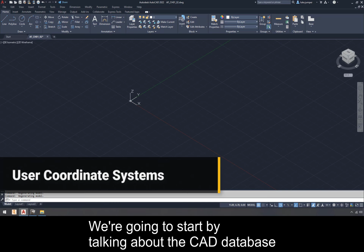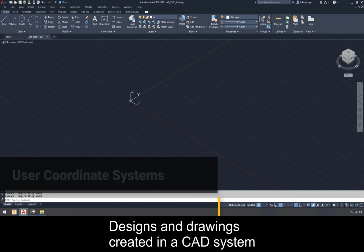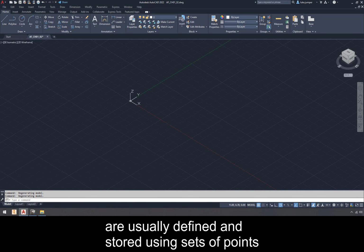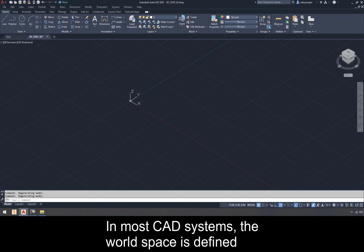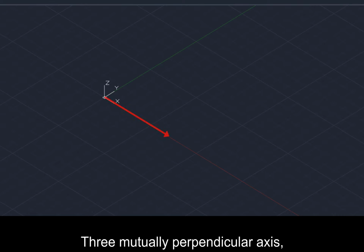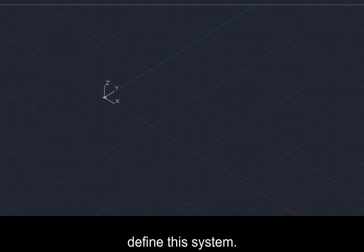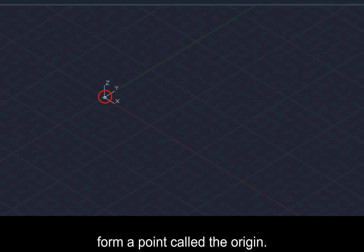We're going to start by talking about the CAD database and the user coordinate system. Designs and drawings created in a CAD system are usually defined and stored using sets of points in what is called world space. In most CAD systems, the world space is defined using a three-dimensional Cartesian coordinate system. Three mutually perpendicular axes, usually referred to as the x, y, and z axes, define this system. The intersection of the three coordinate axes form a point called the origin.